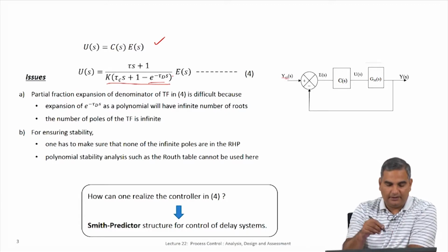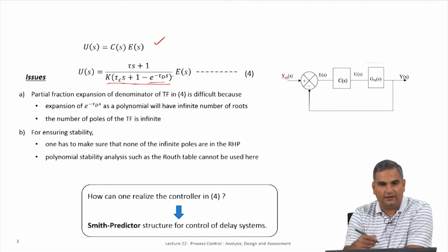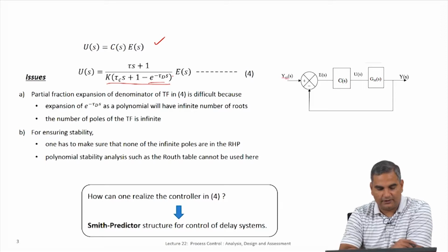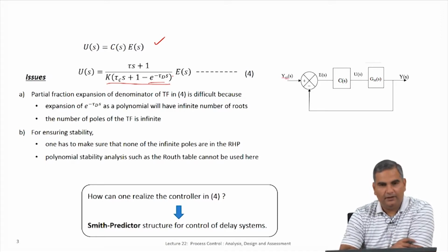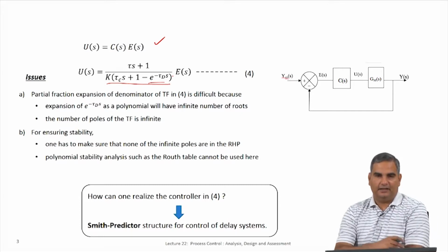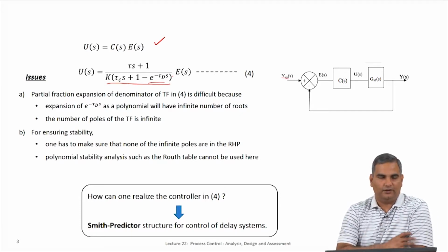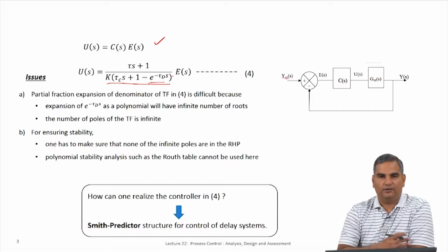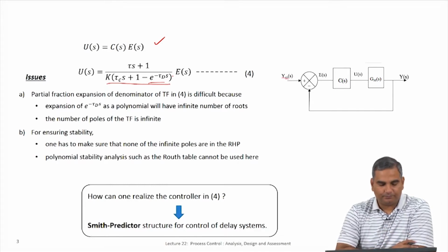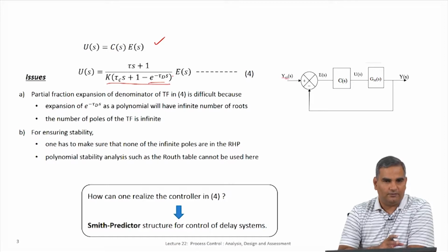So, basically all of the computations we have done using partial fractions are not possible anymore, is the first thing that I want to explain. And number 2 is that if it is a simple partial fraction, then we know how to do stability, right. We get it in the root resolved form and we look at all the roots. If all of them are in the LHP, we say the system is stable. However, because partial fractions are not possible, we cannot do that for stability.